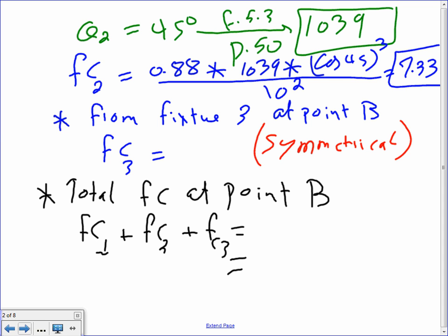Andrew, I want you to see, even though you got more lumens, can you guys see that? Even though you got more lumens at 45, at the nadir point you get more light because of the cosine of the angle. Does that make sense? Right underneath the fixture will get you more light, more foot candle. Even though you got more lumens, that lumens will disappear because it's further distance. Any comments, any questions?